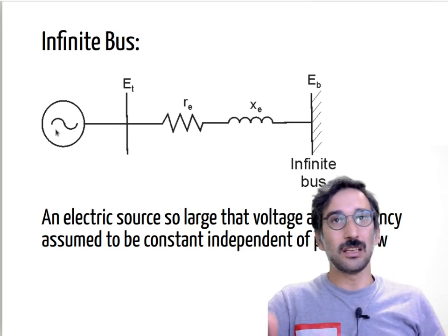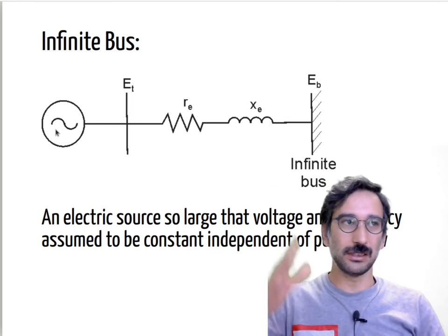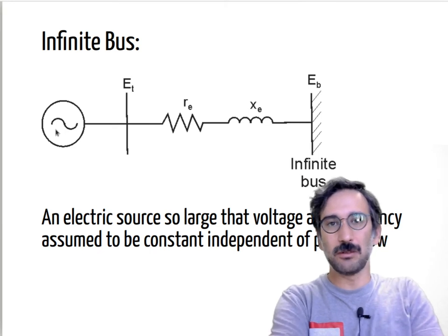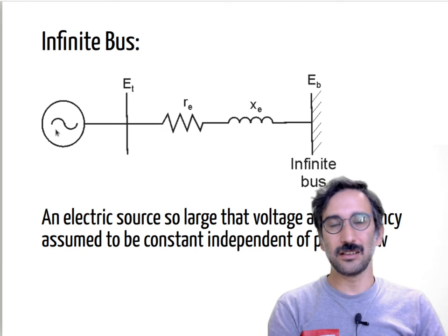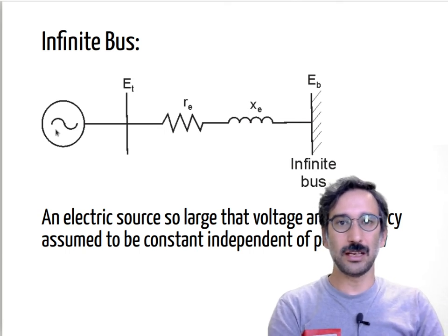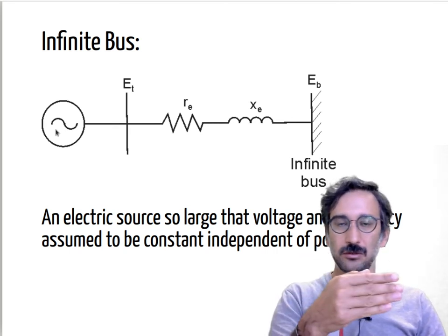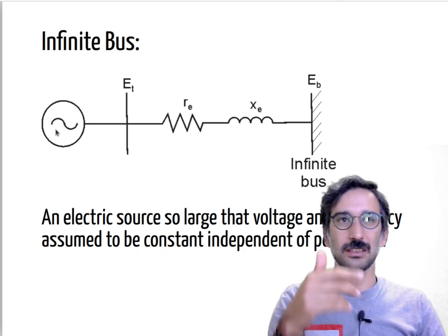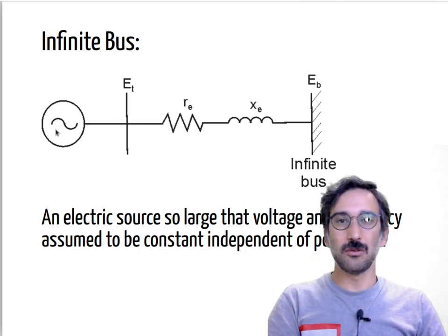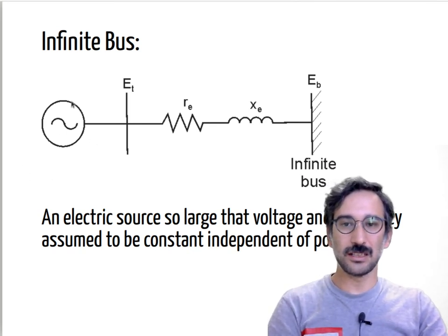Or if you have a wind turbine, most of them nowadays are controlled by power electronics converters in between, so they don't have to be exactly at grid frequency, but there are some early examples where the generator is connected directly to the grid. If you stay connected even when there is no wind, your wind turbine starts working as a fan, blowing air, so the whole system works as a motor.